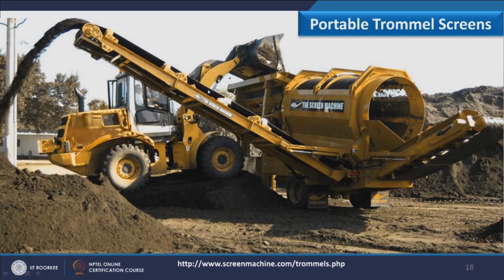And this is the portable trommel screen. The link is available here for detailed study of this particular screen. Here we have the feeder, in which feed continuously enters, and then it enters the trommel. The continuous rotation of the trommel takes place, and the finer particles are collected by a belt conveyor at one side, and the oversize is collected at another side by another belt conveyor. So, it is a portable screen which can be taken to any place where such screening is required.